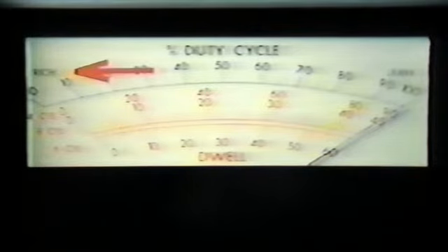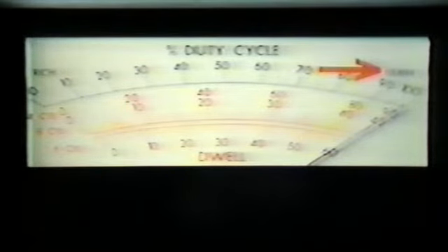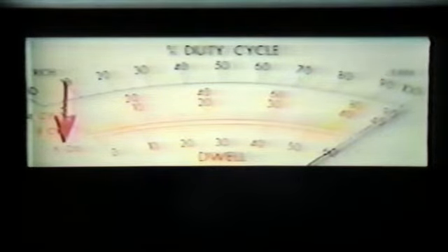To see what's going on inside the carburetor, we can simply hook up a dwell meter to the test connector. The dwell meter measures the time when current is flowing and tells us if the carburetor is running rich or lean. Once the dwell meter is connected to the test lead, we set it on a 6-cylinder scale. It doesn't matter how many cylinders the engine has, because the 6-cylinder scale provides us with a 0 to 60-degree meter reading. Now, with the engine running, and considering 60 degrees as a full 1/10 of a second, we can see what the on time is in the solenoid.